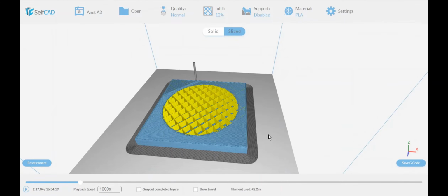What this means is that if you want the object to stick onto the printer, often, especially if you have tiny objects, small pieces, the force from the nozzle as it moves will influence this, and it may actually move it. It's not sticking enough to the build plate, and it may shift and mess up the entire printing. So the idea here is that you add some thin layer first. The word adhesion is used for scar tissue and things like that, which puts it into context. It's adding a very thin layer, something that sticks things together. This is meant to be removed later, but it gives the object you start printing something to stick onto. So that's basically the idea.